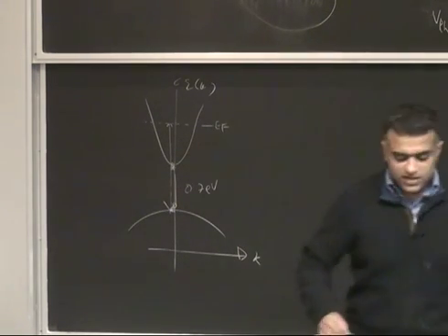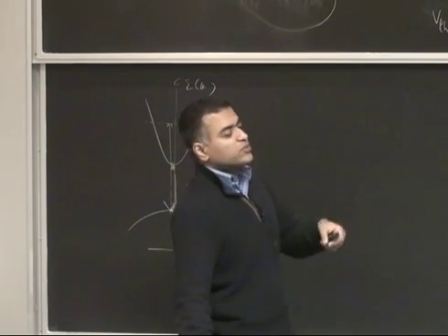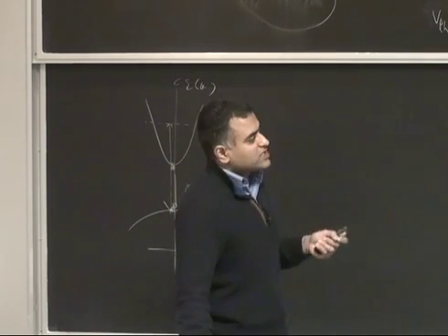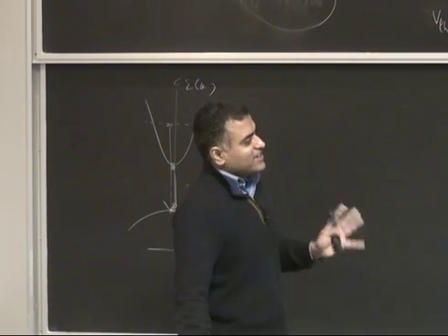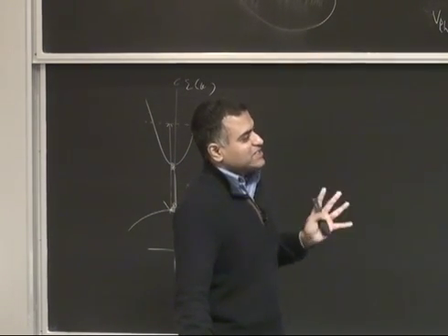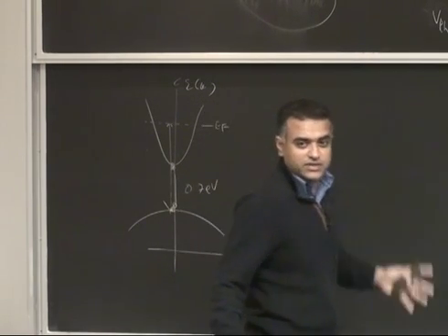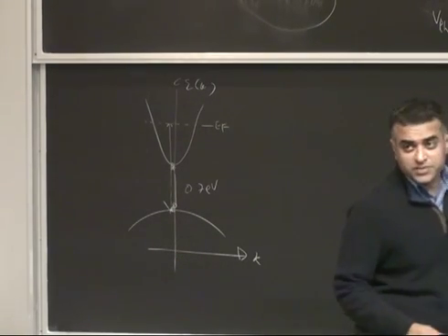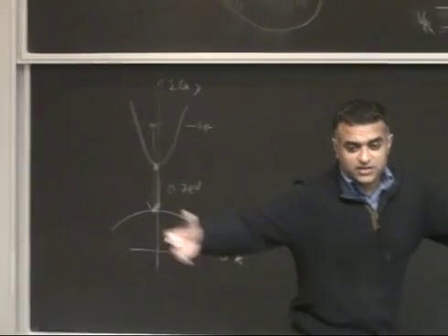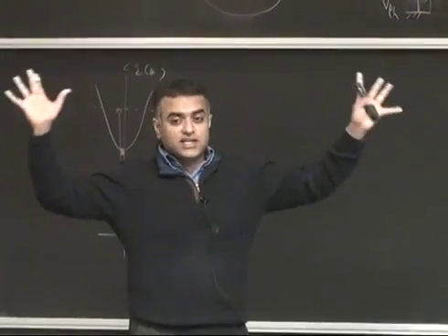It turns out that in addition to being very efficient light emitters, the nitrides are also very robust, meaning the light emission process, because of a confluence of many intended and unintended reasons, it is very difficult for this material not to emit light. It just wants to emit light, even in the presence of defects and all that stuff. So that is one of the important properties of the nitrides, which is why it's now the framework for all LED and laser, a lot of solid state lighting and that.